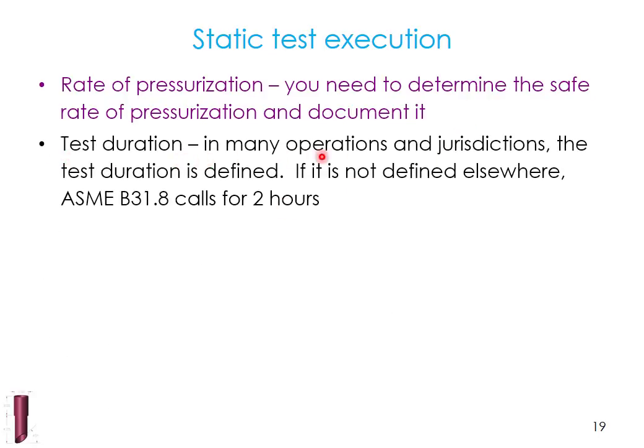Test duration. In many operations jurisdictions, the test duration is defined. A company will say all tests have to be for 24 hours. A jurisdiction will say all tests have to be at least 5 minutes. If it's not defined elsewhere, then the ASME B31.8, which is the gas code, calls for 2 hours.